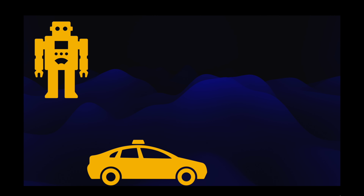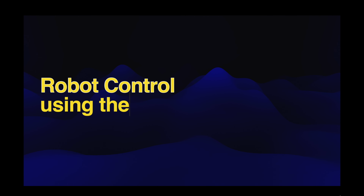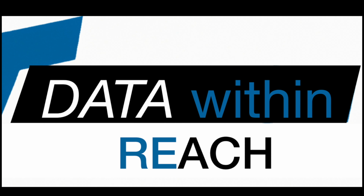Today, we're going to create a robot object, and we're going to define a run function that uses cross-track error and a hyperparameter called tau to minimize the error in the steering input such that it travels in a stable fashion. And we'll play around with that hyperparameter to get the robot to move both in a stable way and an unstable way. We've only got about 3 minutes, give or take, so hey, let's get started.